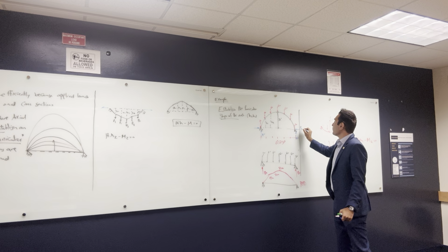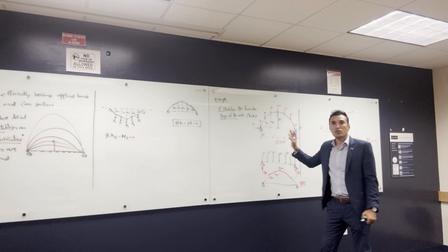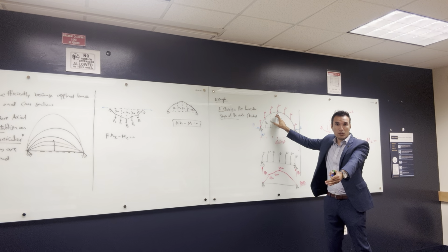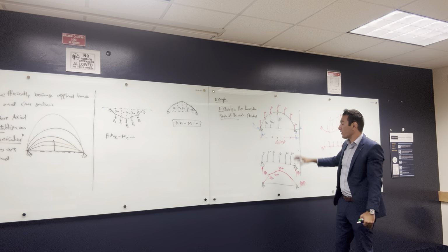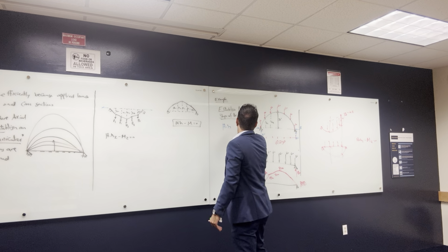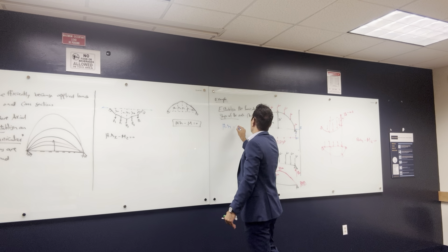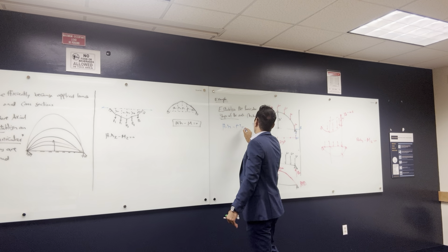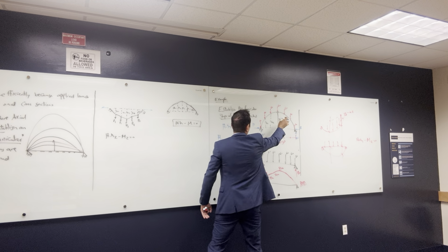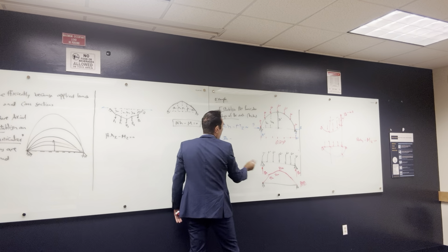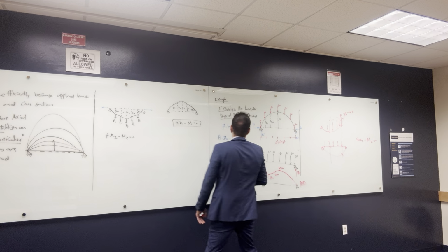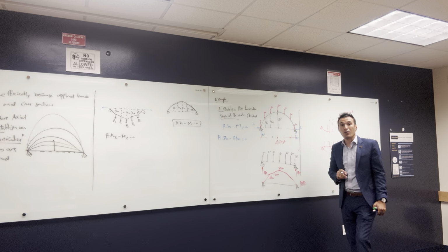So to get the horizontal force, there are different ways. Actually, there's one way: you have an intermediate hinge here, take all the moment from the left equal to 0, and you can solve this. However, I can actually use the general cable theory. It says that H multiplied by h minus Mz is equal to 0. So I want to know the horizontal force, H, and I know this h is 36, minus the moment in the middle, which is 8,100. All this is equal to 0.